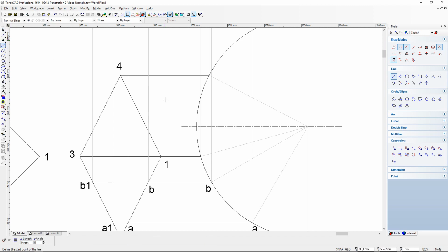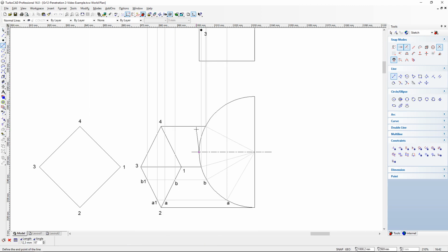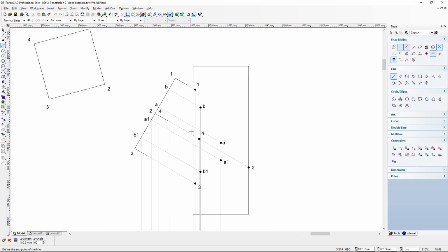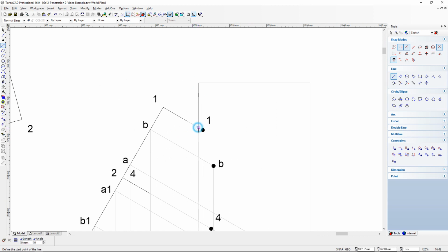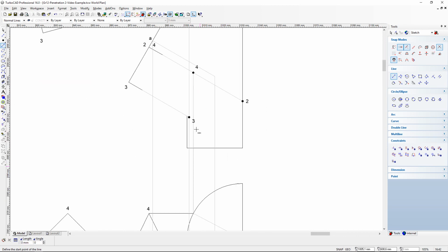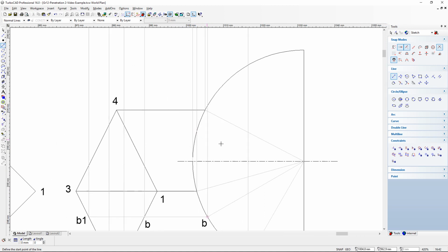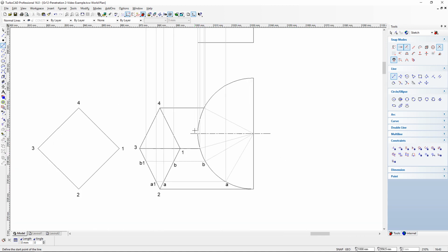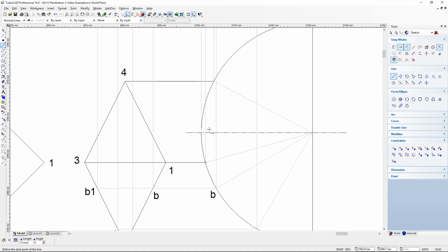So I'm going to take a light construction line and place a light construction line from that intersection or center point vertically up. So you will see now that it lines up perfectly with the front view's edge. Okay, because that will give us the radius from the center to the very edge of our cylinder. So what we need to do now is to determine exactly where that will start to become hidden detail.